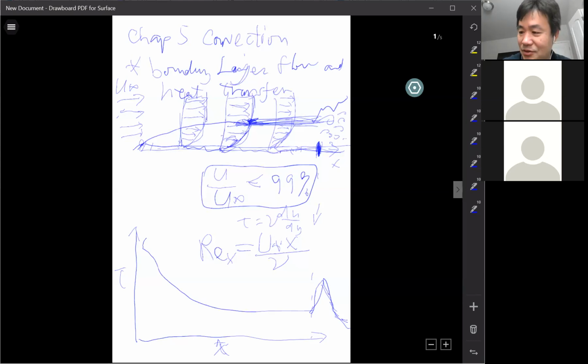Okay, so you see, this Reynolds number is not a certain number. It's not like in the pipe. Each pipe flow you have a Reynolds number because there's a diameter that doesn't change, right? Here, which means that at every location on the plate, on every different x, you will have a Reynolds number. So at the beginning point, your Reynolds number is really small. That makes sense. In the beginning, it's very viscous. Then gradually, at later locations along the plate, you have a higher Reynolds number.